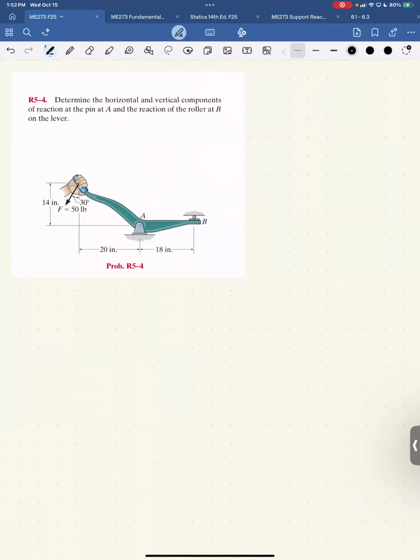This one's really almost the same. We'll just do it. So free body diagram, I have a roller at B, so there's a normal reaction. And I'm just going to draw it up even though it's down, but it's fine, right? There's a reaction at A, we have a pin, so there's AY and AX. Coordinate system, X, Y. Count unknowns, I have 3 unknowns. So I'm good to go.